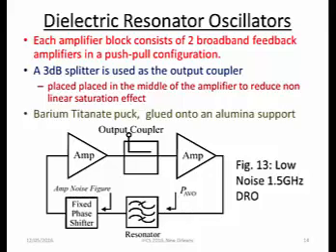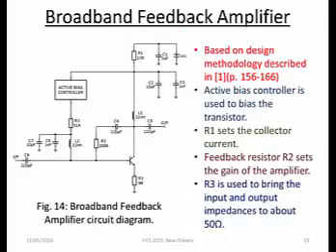One important thing to notice is that we measured the noise figure of the amplifier at the points where the whole loop connects to the resonator cavity. So in the measurement, everything was included from both amplifiers, the output coupler, the phase shifter, and also all the cabling. This is quite important because when we plug the noise figure into the theoretical model, this will make it agree with the measurement better.